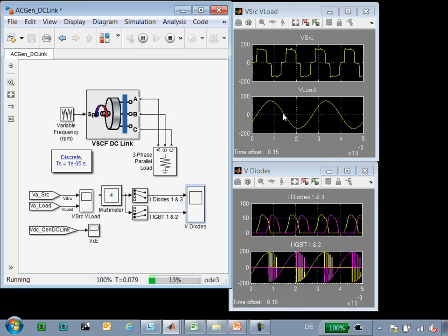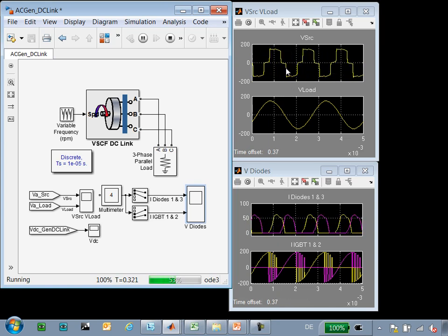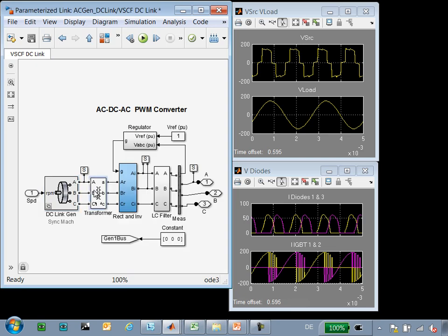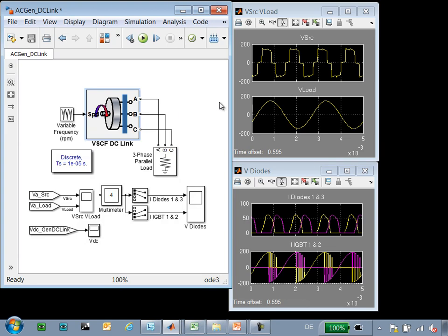Here you can see that the output frequency is still fixed, but we can see that there's a bit of a problem at the generator. The power electronics are drawing different levels of current at different phases of the cycle, and this is resulting in the voltage on the phases of the generator not following a clean sine wave signal. We could resolve this problem by taking this transformer and replacing it with zigzag transformers, and that would allow us to compensate for the current being drawn.